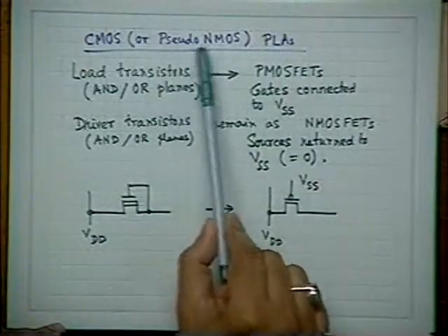But in this case, what are we doing? If all the driver transistors maintain a ratio of 1/1, then the load transistor ratio will be simply 2/1. And load transistors are only few in number, but the bulk of the operation is carried out by the NMOSes. Therefore, there will be a tremendous reduction in area if you use the so-called pseudo-NMOS.